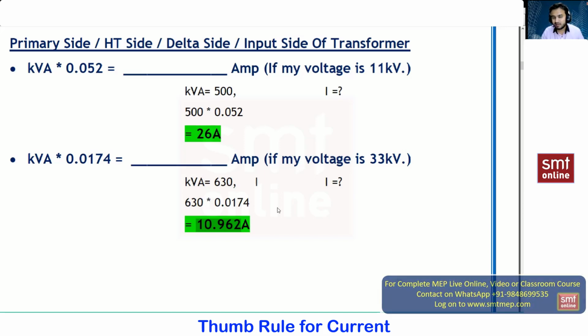Like I'm having a load of something like 30 kVA. And for this 30 kVA of load, whenever there is any kind of interruption from the transformer supply, I need a backup for minimum 30 minutes. So in that case, I have to find out the ampere hour. There the term hour generates.